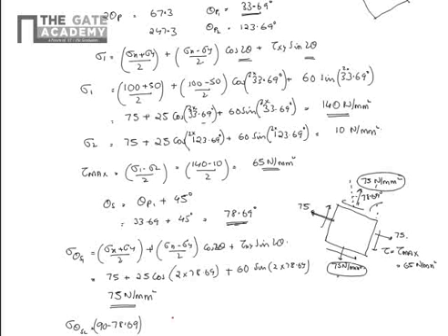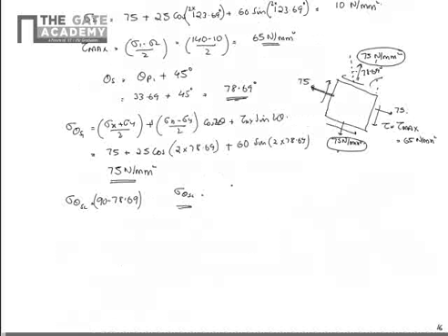If you substitute that value, you can get a value of sigma. That means when the shear stress is maximum, that plane will also have a normal stress. Normal stress will not go to 0. It will have a different value of normal stress also. But for principal planes, the normal stress is maximum and the shear stress becomes 0.